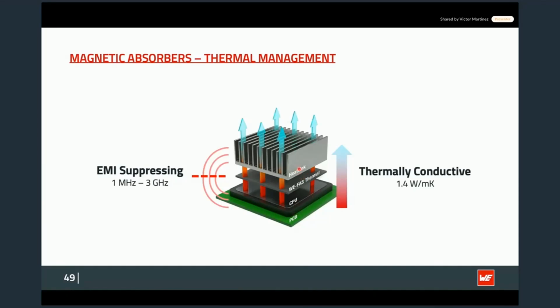So you have over here a metallic surface, a blank space, or air, and then here you have another metallic surface. So you have over there a capacitor. And then that capacitor can create some unexpected problems that maybe you didn't think about in advance. Probably the first way to act will be, okay, maybe I can remove the heatsink. And then your colleague from mechanical engineering will reach you and say, don't do it. The whole thing will just melt. So then the heatsink is a must.